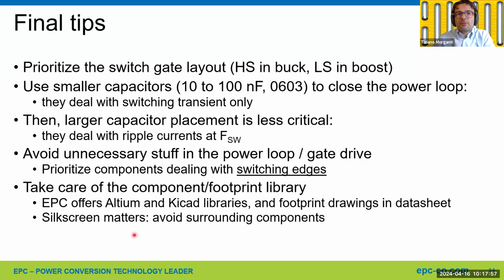In some cases, if you surround a component with a silkscreen box, the flux flow during reflow is made more difficult, and this can have an impact on the soldering process and the cleaning of the board after the reflow.